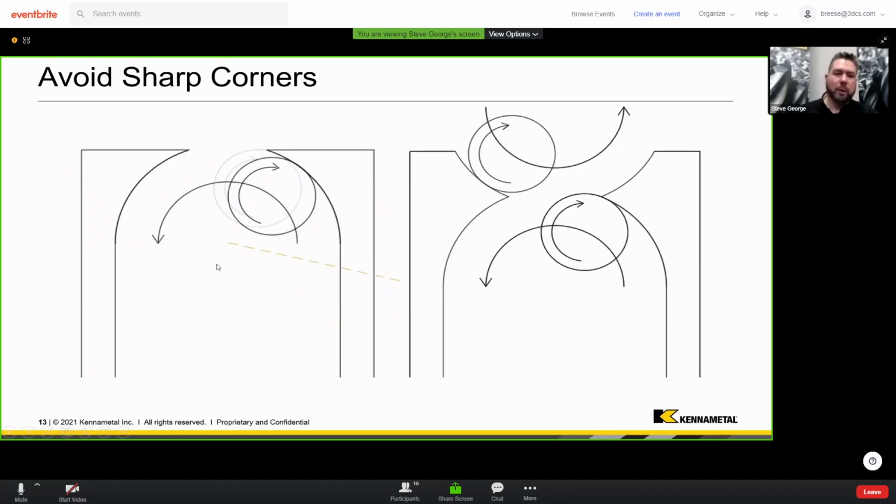Avoiding sharp corners. This is an application example from some aerospace customers of trochoidal milling, and what happened at the end. So they're using trochoidal to make a slot in a dynamic fashion. Once they break through the end, now you have a significant amount of deflection here. The cutter's rotating this way, can come back and snap. You can think about things like, if I came through and roughed this out a little bit from the other side, or if I stopped before I broke through and came back from the other side, how can I minimize some potential danger areas?